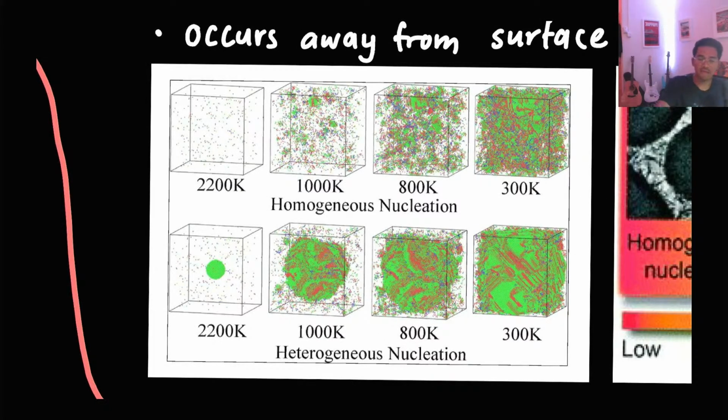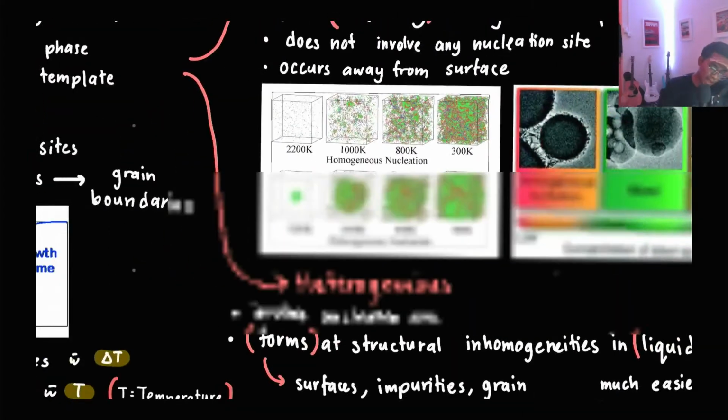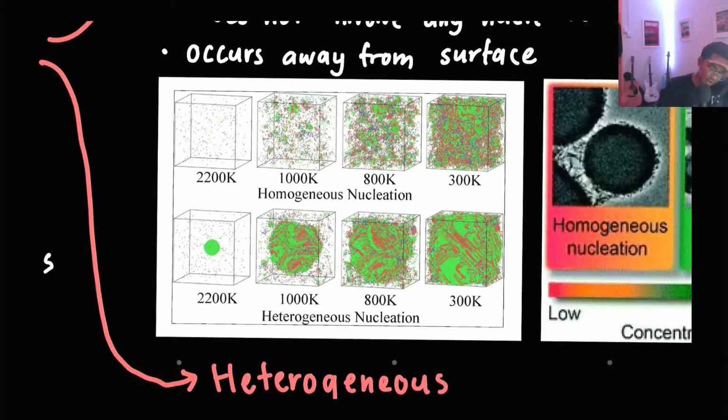Nucleation is when you have a material, then when that material cools down, the liquid phase of the material starts having certain points emerging from the middle of the liquid. Those points are called nuclei, nucleus. So there are two types of nucleation: homogeneous nucleation and also heterogeneous nucleation.